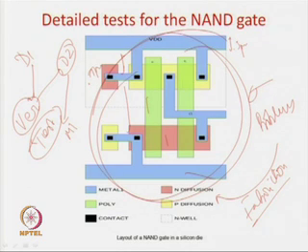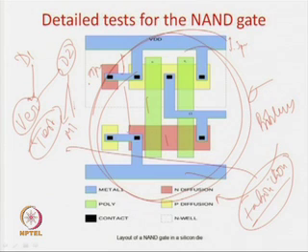Now, this fabrication or manufacturing process has a lot of imperfections, and we will slowly see why. Because of these imperfections, this M1 may not be equivalent to your D2. So, the testing procedure basically tests whether there has been any problem in the manufacturing step, such that M1 does not become equivalent to D2. Truly speaking, you would have to find out whether this has been properly laid out, whether this thickness is proper or not, and the test equipment and the test time would be enormous, exceptionally high, if you go for a test at this level.